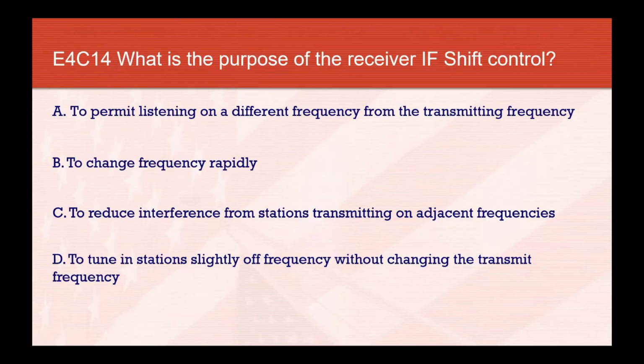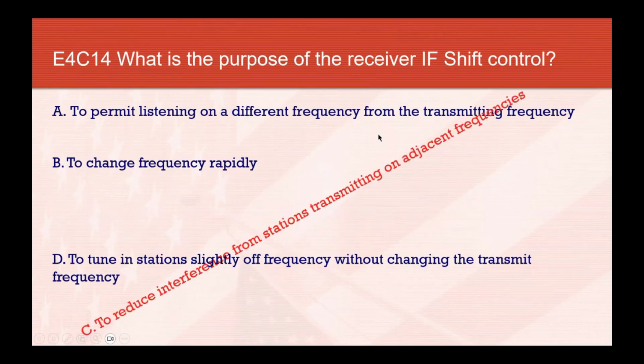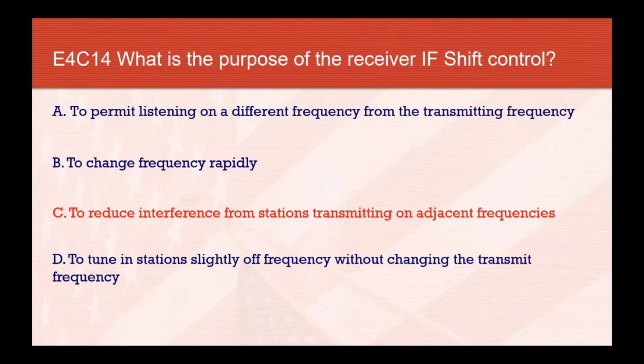Purpose of receiver IF shift control. Let's just move that receive spot up or down a little bit to reduce the interference from nearby stations, people that are transmitting on adjacent frequencies.